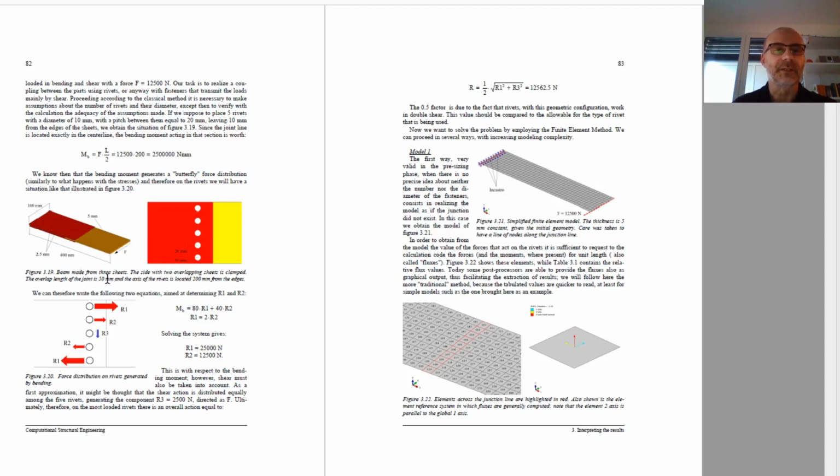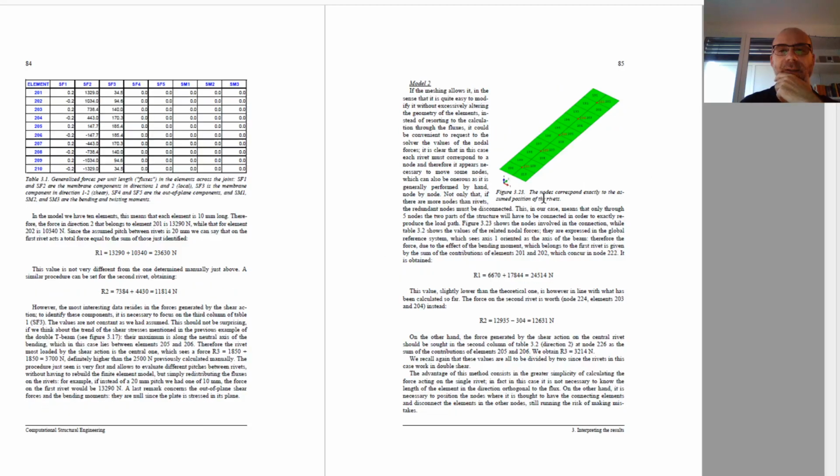Another example here is presented as if we want to connect these 3 plates with rivets. The first simple model can be done with just one shell because it's a preliminary estimate. To understand how many rivets and what is the force which would pass through the rivets, here is shown how to use the fluxes in the shell elements.